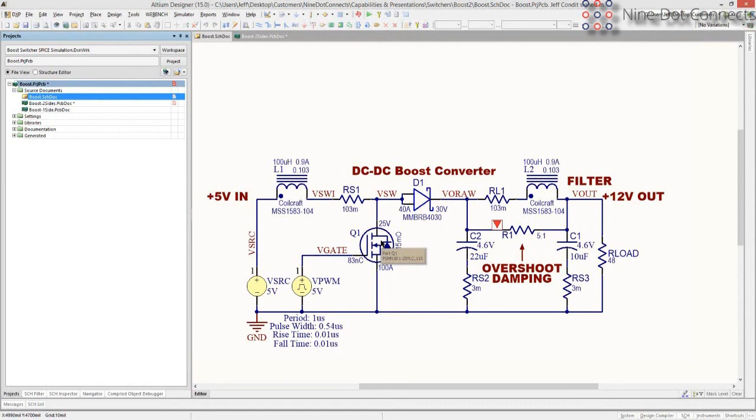Rather than having very thick copper in the hole or studs in the hole, you may choose instead to have an array of vias. That's commonly done.